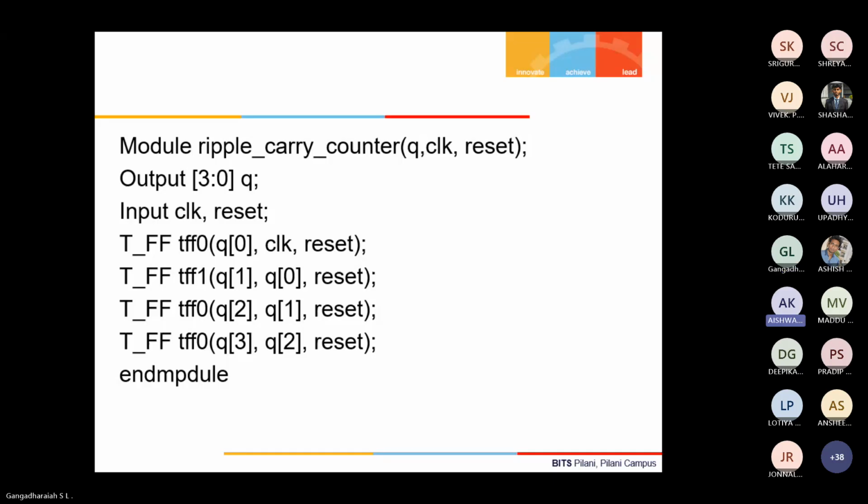But sir, in behavioral modeling, we usually declare reg. Whatever input is there, whichever is required to be declared as reg, we'll declare it as reg. But I have never seen declaring a wire inside the RTL. Wire was just used in the test bench, so I had a doubt. No. Wire by default is supported, of course. Even if you don't mention it explicitly, all IOs are wires by default.